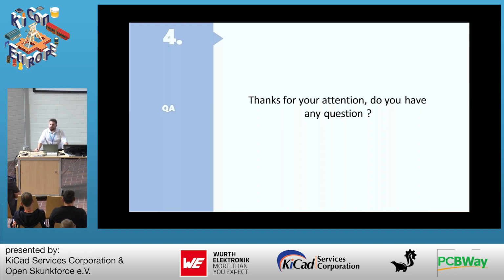We created a new tool, something like 3 or 4 months ago, to help our customers calculate, regarding our standard stack-up, the width of their lines to match the impedance they want. We have this online. You just have to search on the internet for PCBWay impedance calculator, and then you will have all the values.